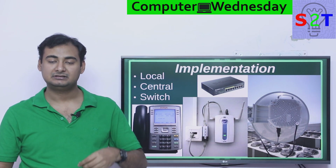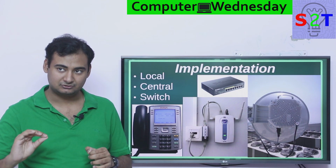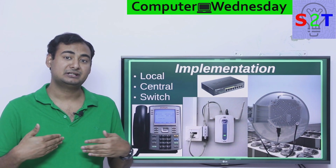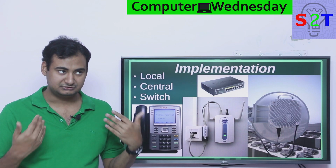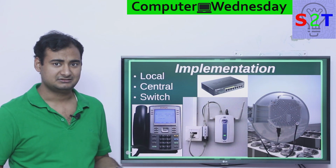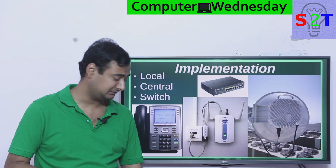Basically you can extract the power and then connect in the data port. It won't fry anything, and that DC output you can connect to your router. So that way you can make anything that is not PoE enabled, PoE enabled. You can simplify the cable management. Now is it good enough to use? That's up to you. So this is how we implement it.